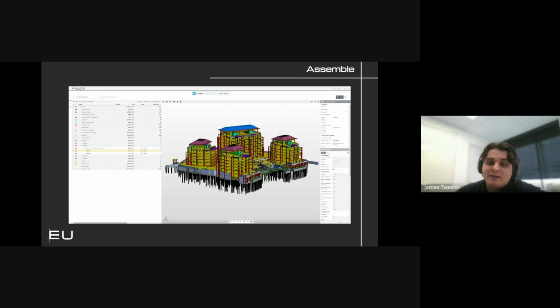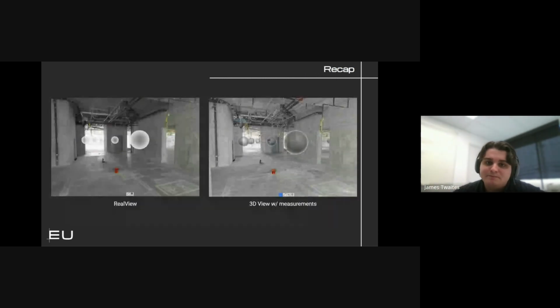And so, for example, on a structural steel project, it's very straightforward to use a platform like this to filter by the weights of the individual members to understand exactly where and when your biggest lifts will be. So this gives you access to not just quantity information, but quantity information that's flexible enough that you can get the information that you need out of it early on in a project.